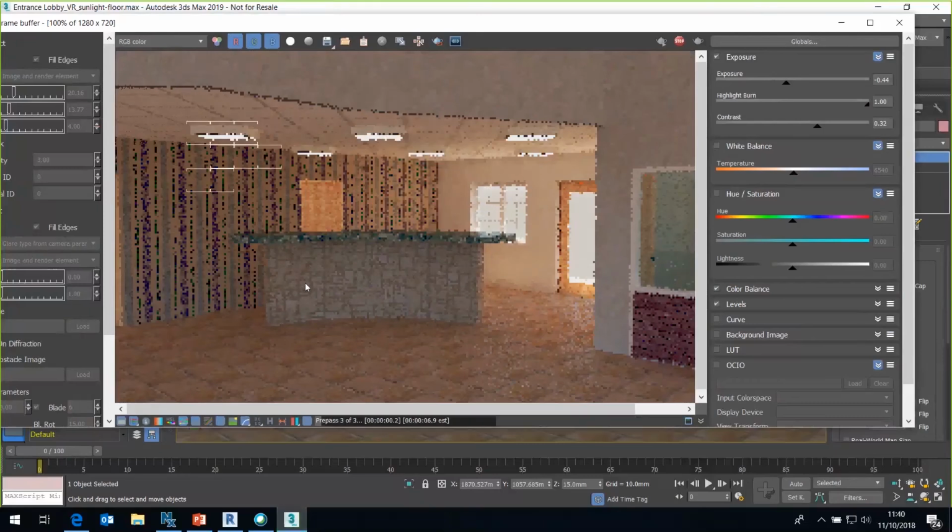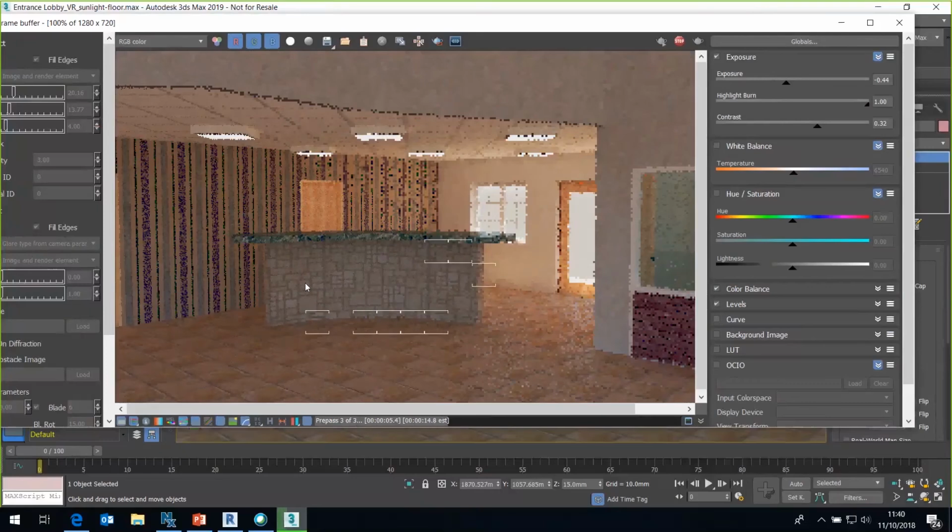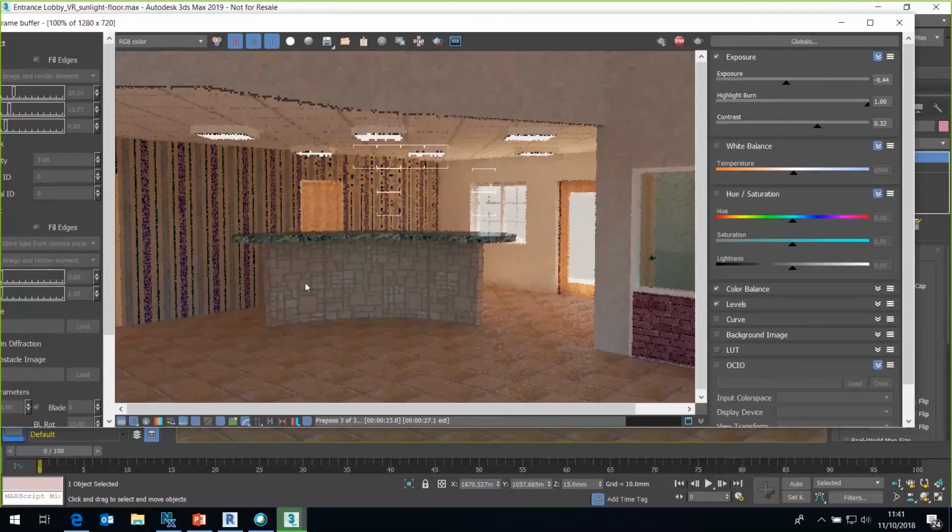reflections and refractions, those type of things, they all introduce a blurring effect, and that puts a lot of processing time onto the render. So what we do also is have a concept called a denoiser. So the denoiser actually looks at surfaces like the flat walls, the floors, and creates a mask around there, and then would create a mask that we would use like a Gaussian blur on there just to clean that up.